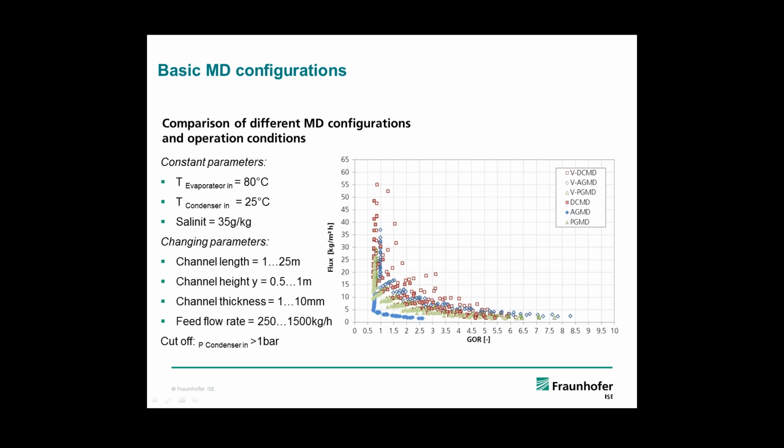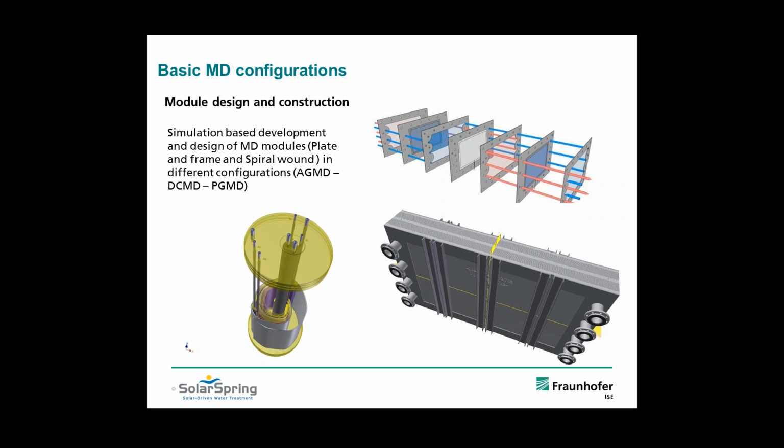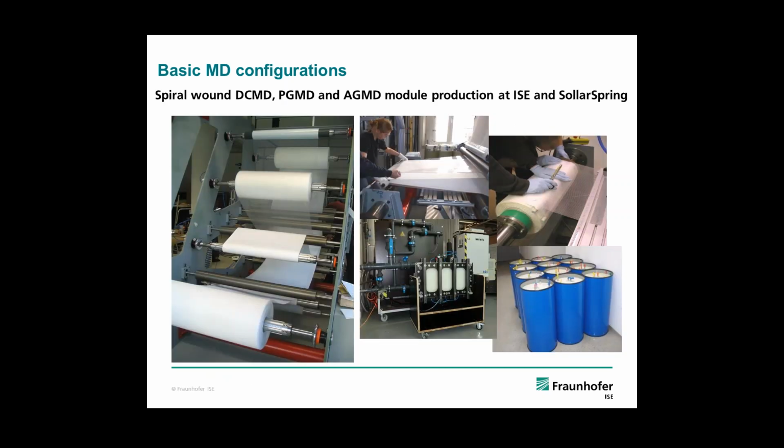One of the most important properties of a sophisticated thermal desalination system today is a heat recovery device. In membrane distillation, you can achieve this when you have very long channels. You see on this slide a membrane distillation module in permeate gap configuration: the evaporator channel on the left-hand side, then the permeate gap where the distillate is collected, and the condenser channel. Assume that seawater enters the condenser channel at about 20 degrees centigrade at the bottom, at number 1.